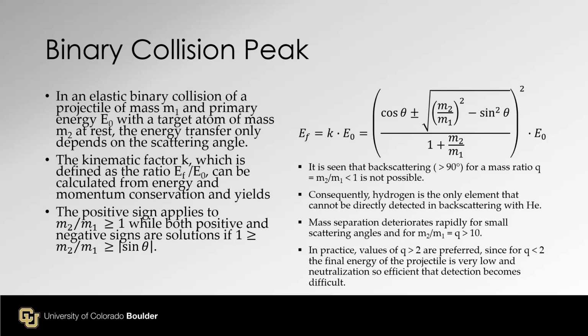And the other thing is when we are using helium as a primary ion, the mass separation, energy separation between iron and nickel, they are too close, okay, with helium as a primary ion. So depending on which elements you want to separate, we have to switch the incident ion type from helium to neon, sometimes if necessary, switch to argon.